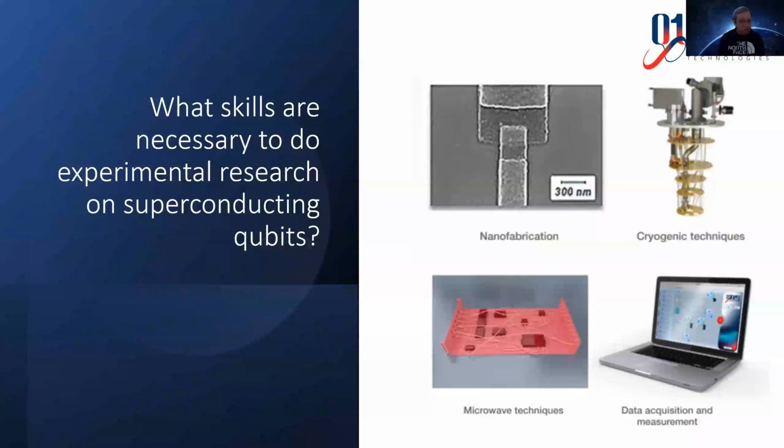Electron beam lithography and photolithography are used to write patterns on a sapphire or silicon substrate, where the wafer is cut into chips using a dicing saw. The electron beam lithography is used to fabricate nano-sized devices such as the superconducting Josephson junction. We will talk about this later, where nanometer resolution is required, something in the range of 50 to 100 nanometers.